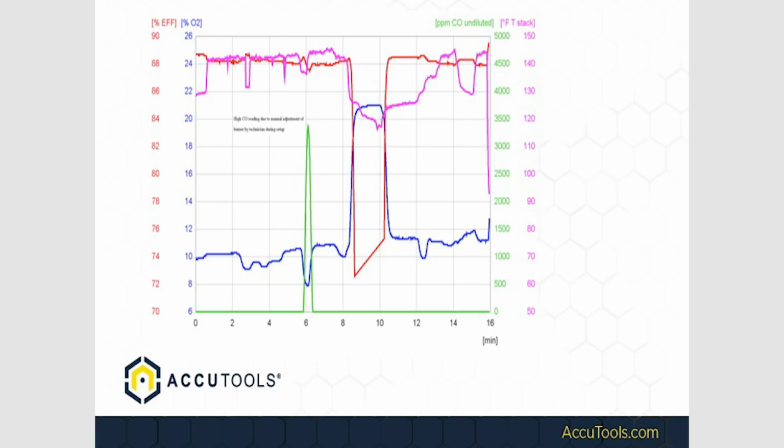The pressure in the chimney was negative 50 pascals. So we had an open boiler space with an open chimney in there, sucking the air out. We have this plunger effect of the elevator shaft going up and down. We have all these perfect series of events that are causing all these problems here. And you can see this is definitely combustion under duress. If you weren't testing this with a combustion analyzer, you'd never see this stuff happening.